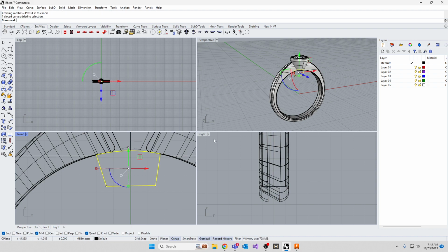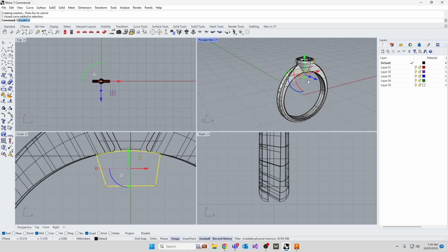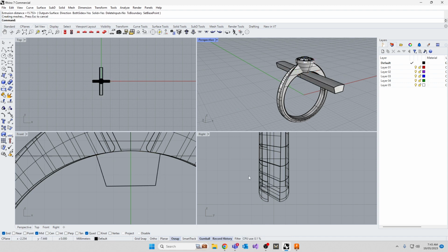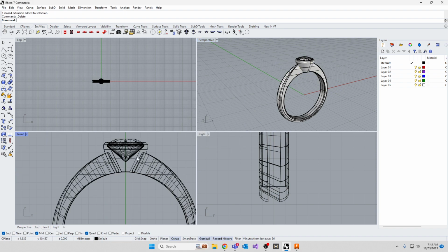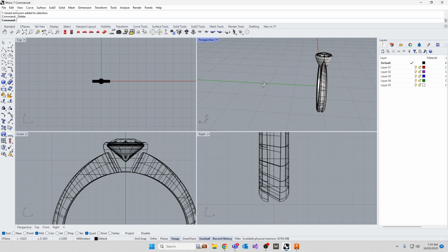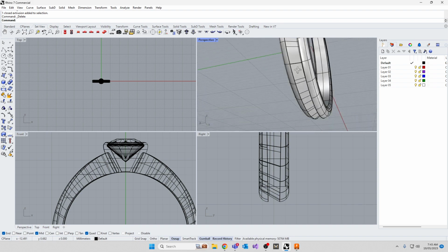What it did in the background is it extruded this, and then it did a Boolean difference between this and this. The shortcut command is called wire cut. Really fast. Sometimes you just want to punch a hole through something. You just want to quickly cut through here. You can quickly draw a curve, and you can do a wire cut. Okay. Oh, this went really poorly for me.